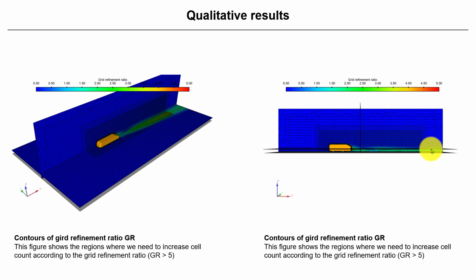Again, remember that in Fluent you have a very nice tool for adaptive mesh refinement, so you can try that tool. However, I will always recommend refining the mesh not using that tool, but your meshing tool, because when you use adaptive mesh refinement, it will add hanging nodes. I'm not a supporter of hanging nodes, but they work. Just be careful when using those hanging nodes.